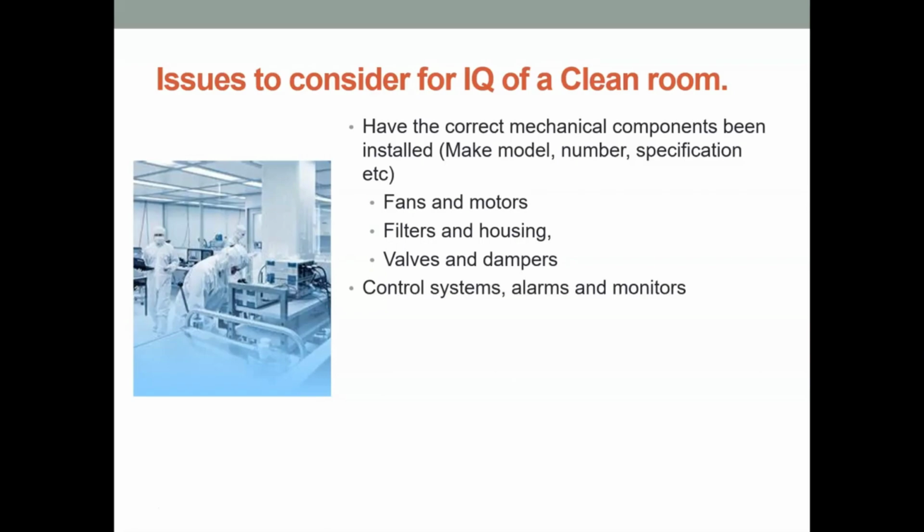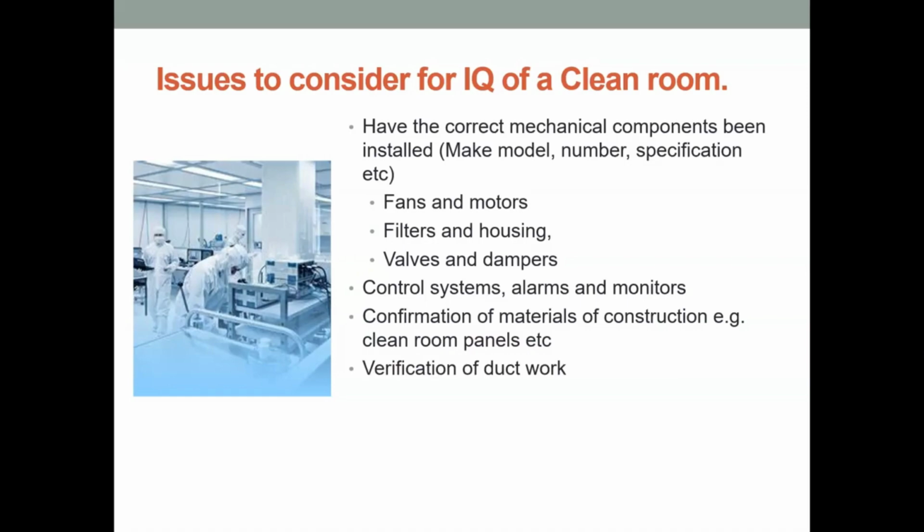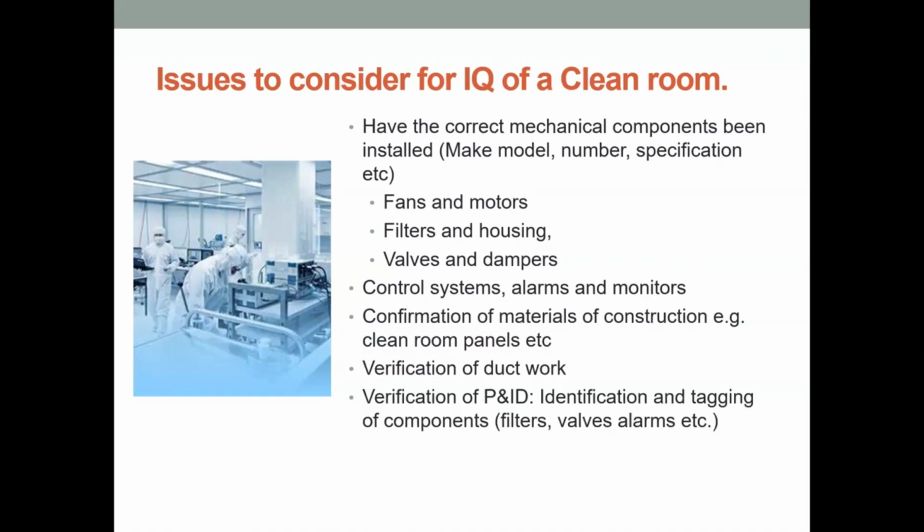Then you'll be looking at the control systems. What alarms and monitors are in place? Are they hooked up properly and are they working correctly? We'll be confirming that the materials of construction, for example, your clean room panels, anything like that, are of the correct grade and GMP certified. We'll be looking at the verification of the ductwork again, and we'll be looking at the P&ID. Are all of your instruments tagged correctly and is everything fitted in the right order as it should be?